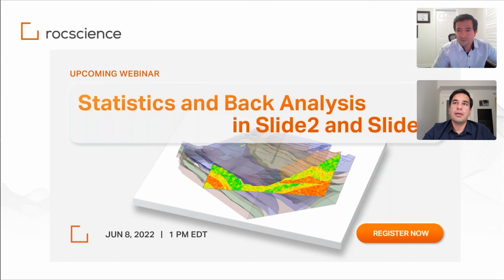Another question that's kind of in my field is best estimate of Norsand parameters. This is a question from Ali: best estimate of Norsand parameters when triaxial data on specific soils are not available. So first of all, in most cases, if you are dealing with a project where you can do Norsand modeling, that probably means that there is enough budget to get a couple buckets of soil and run a few triaxial tests. It's absolutely worthwhile doing that because it tells you a lot, not only for your modeling, but about the material you're dealing with.